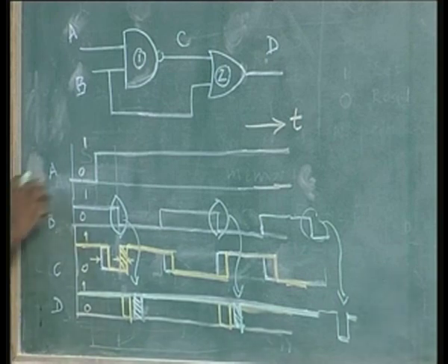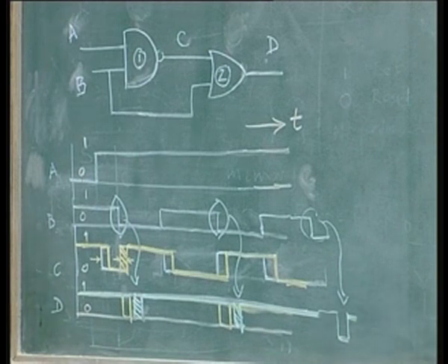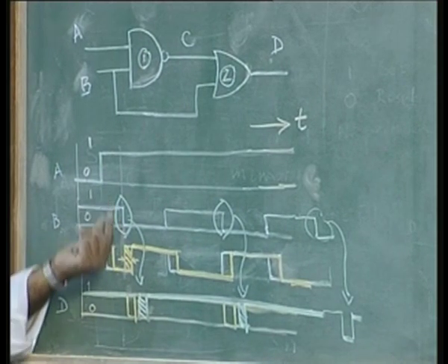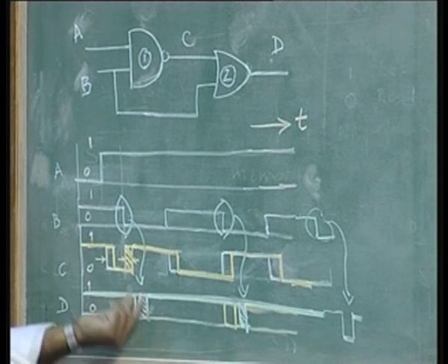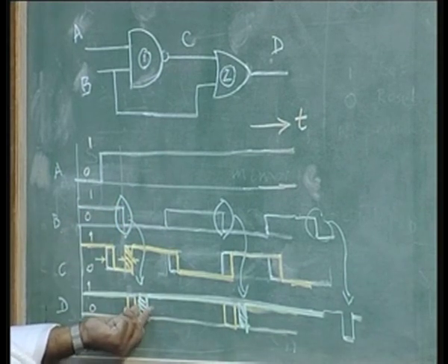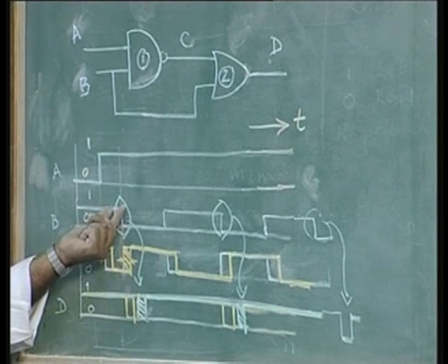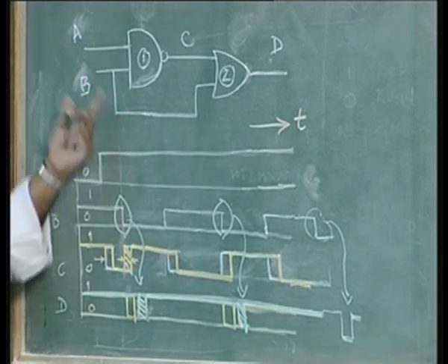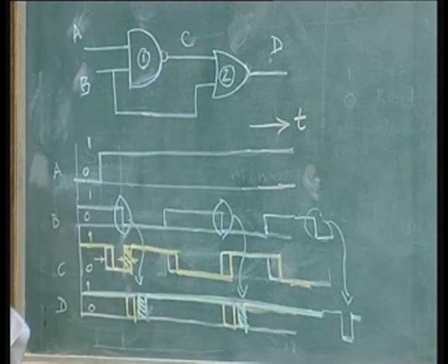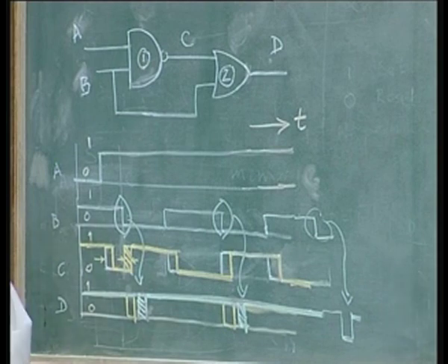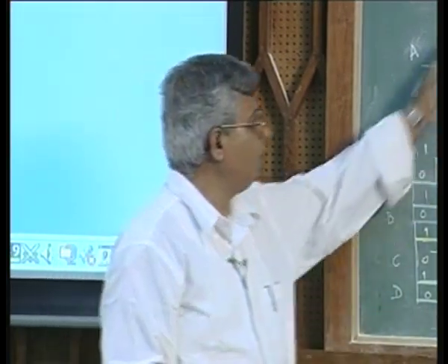So, what I want is, corresponding to the input which is constantly 1, narrow pulses every time the clock changes. Every time the clock changes, in this case from positive to negative, that means negative edge, the output becomes a small pulse. Now I can change this into a positive pulse, as I said, by changing the configuration of the gates. I can make this pulse positive edge triggered by again making some changes in the circuit. So, I can have a positive pulse at positive edge, negative pulse at positive edge, negative pulse at negative edge, whatever is the combination I want, by different types of gates.